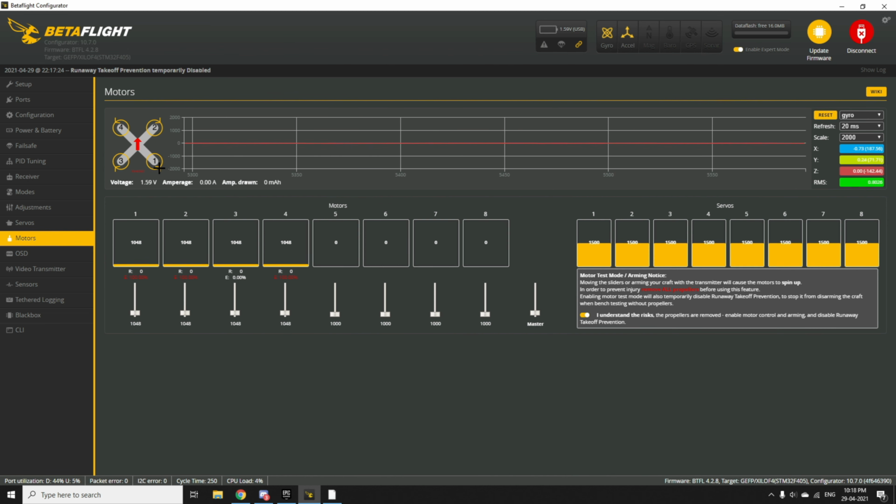So the bottom right motor should spin counterclockwise, number 2 should spin clockwise, 3 clockwise and 4 counterclockwise. So this is the reverse direction. If you have the normal, all of these will change. So the first motor will be clockwise, then this would be counterclockwise and clockwise. So you need to check that every time. But then you need to check your motors. So say I turn on motor 1 and it spins motor 4.